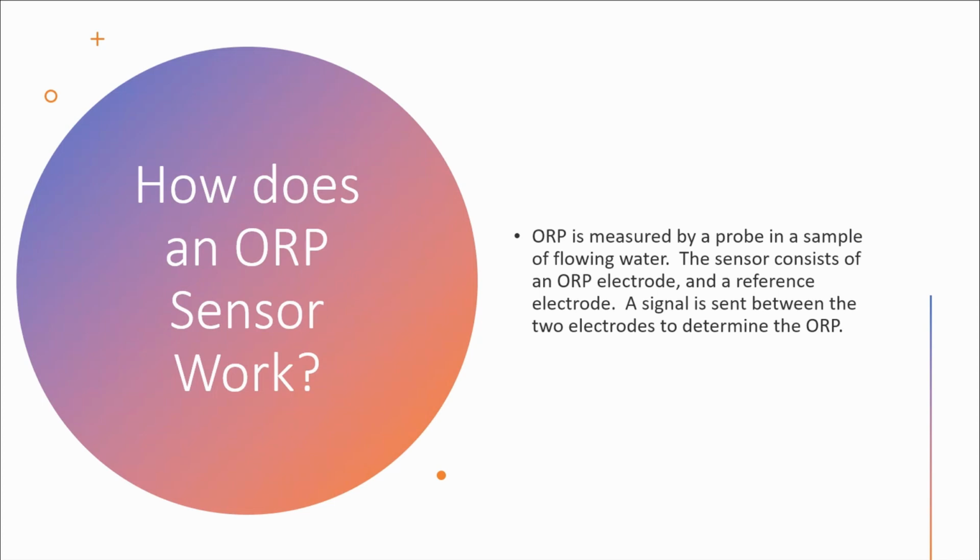There's also a temperature probe in this because there's a correction for temperature. The one nice thing about the Hach ORP probes is you can pull temperature right out of the same sensor, which is also an indicator when the probe goes bad, when the temperature sensor doesn't read right anymore. A little tattletale we've learned over the 10 years we've been running this system. Well, that's good.